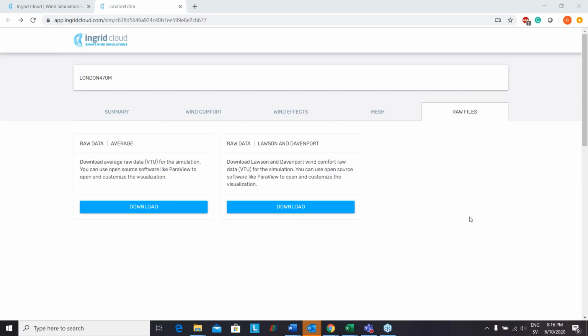And the mesh report of orthogonality and skewness, well, the mesh quality is ensured by the mesh algorithm you're using. And as I said, if you want to have more control, you can download the mesh and have a proper view on the mesh to see if the mesh or simulation corresponds to the accuracy you want.